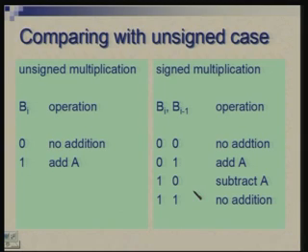So, with this small change introduced, all the circuits which we had could be made to work for signed multiplication. Okay. The only thing we need to remember is that what we had shown as adder needs to be capable of performing addition and subtraction. And there has to be a little logic which looks at the pattern of b i and b i minus 1. It looks at 2 bits and decides, instructs that circuit to perform either no addition, addition or subtraction.